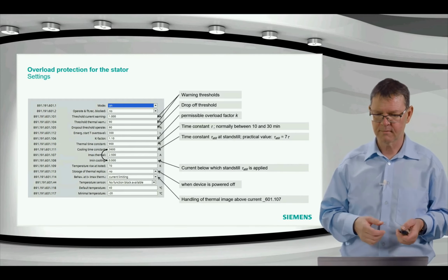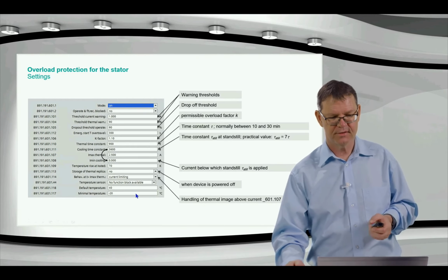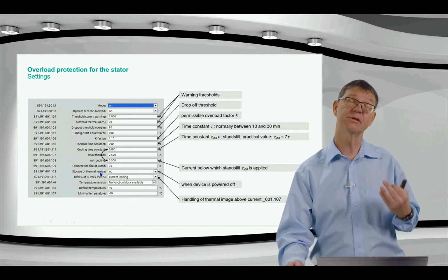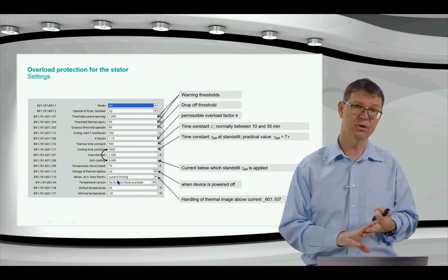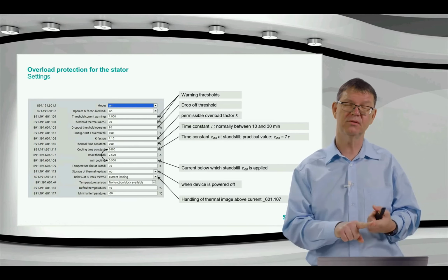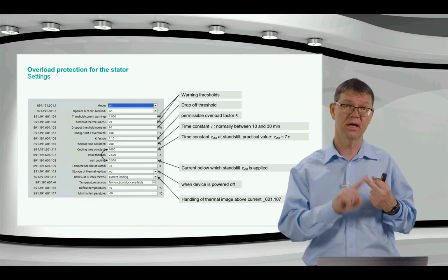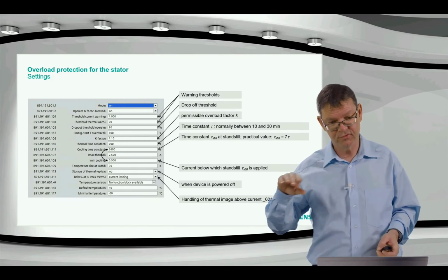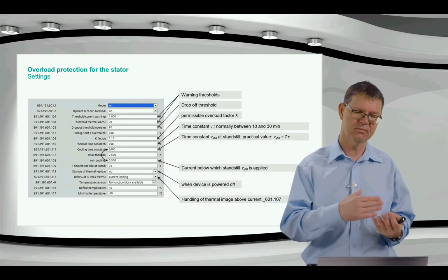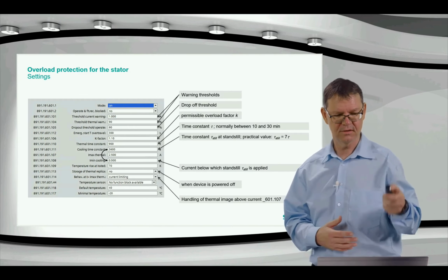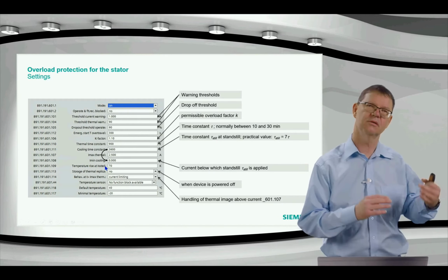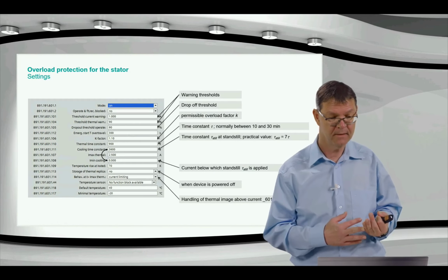And we have one more thing. If the current is too big that goes into this thermal model, since this is just an approximation of the real situation. So if we have a fault current or if we have a very long, heavy startup current and before the motor was already running, so there is already a temperature, we could have an overfunction. That means during the startup, this here would go over the 100% and trip because we consider a high current here.